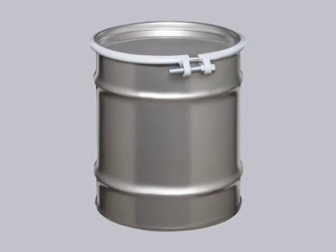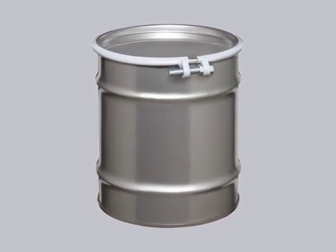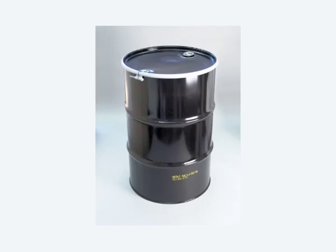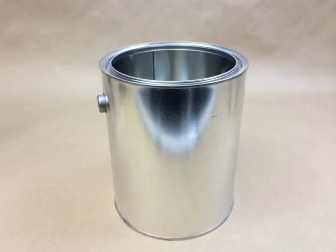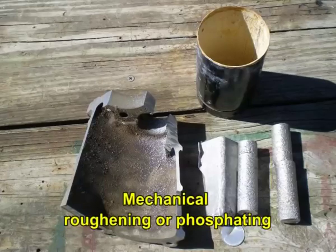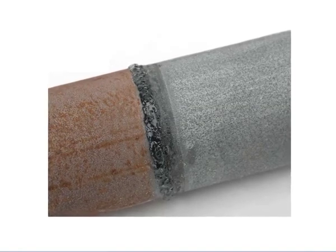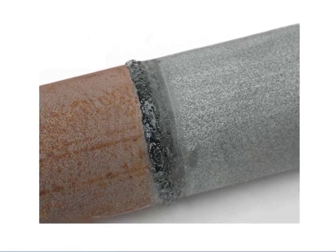This is particularly important for belted drums, where the welding process destroys the original coating of the sheet. The container is then stoved to cure the resin. The efficacy of the coating depends to a large extent on correct surface preparation, that is, mechanical roughening or phosphating. A phosphate coating is frequently used externally prior to decoration.